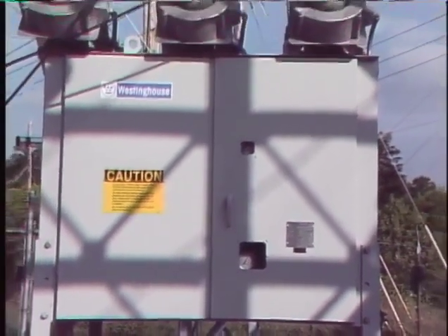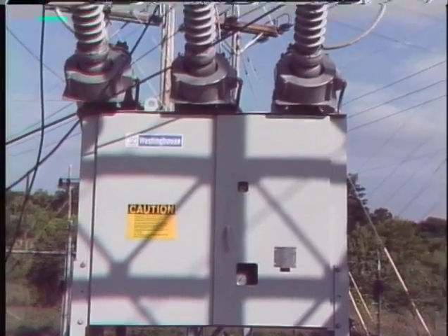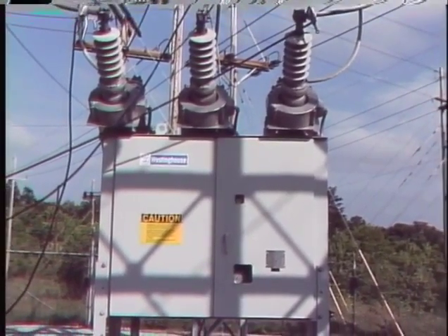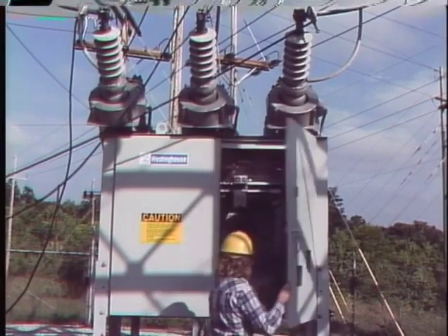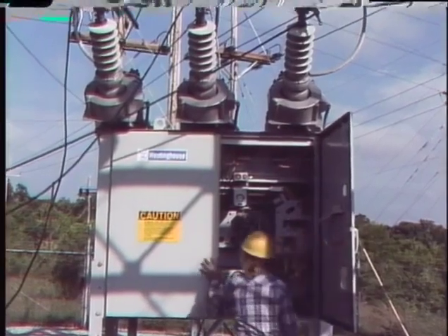Maintenance for solenoid and motor spring operating mechanisms generally doesn't involve much more than the normal cleaning, inspection, and adjustment checks. However, maintenance for pneumatic and hydraulic mechanisms is more involved. Many of the tasks for a pneumatic mechanism deal with its compressed air system. The specific tasks we're going to look at include draining water from the compressed air reservoir, checking the compressor oil, filter, and belt, checking for air leaks, checking pressure switches, and determining how many times the breaker will operate on a full tank of air.